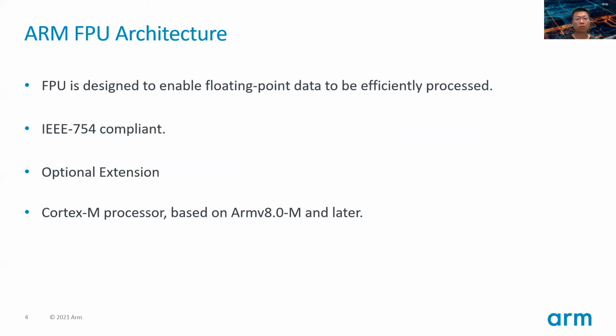ARM FPU architecture provides high performance and high efficiency hardware support for floating-point operations, which is fully IEEE 754 compliant. The FPU is optional in several Cortex-M processors. This presentation is based on Armv8 architecture and later for FP support on Cortex-M processors.